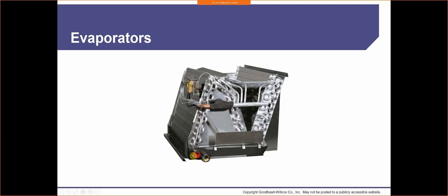I can also put a sensor inside of here so that if my primary gets backed up and my condensate pan starts to fill up, well, the switch will tell the air conditioner to stop operating. And when it stops operating, I'm going to get no more water buildup. All right. As a homeowner, I would then know that I've got no air conditioning going on, and I would have a technician come in to figure out why.